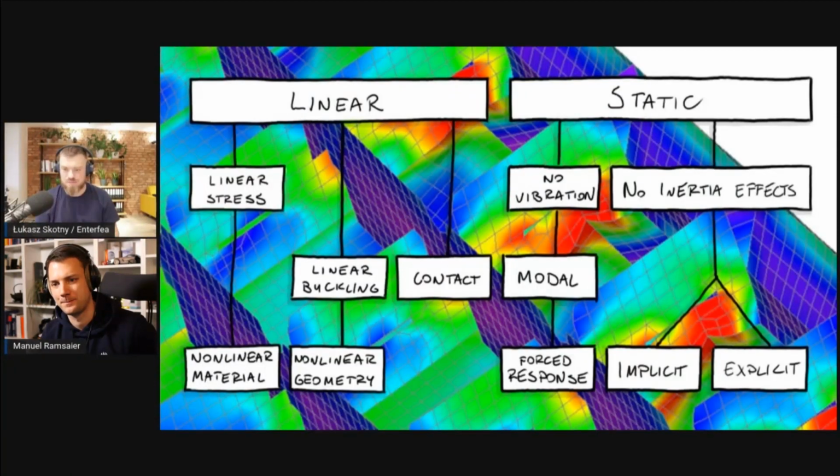So if you think about computing explicit of something that takes an hour, it will never finish. This is not how it works. Of course, you don't check convergence, and it does the mathematics a different way. So each step is super, super quick. But you need to have a lot of those to get anywhere. So this is more or less reserved to super quick things that happen in very, very short time. If you shoot a sniper rifle and the bullet flies and hits something, that's a very quick impact. So that would be a very nice explicit problem.